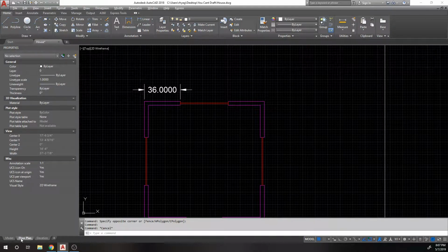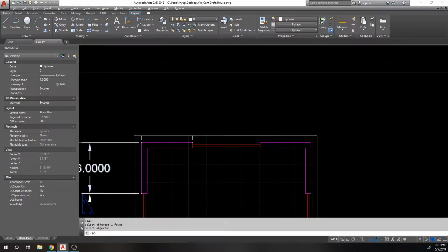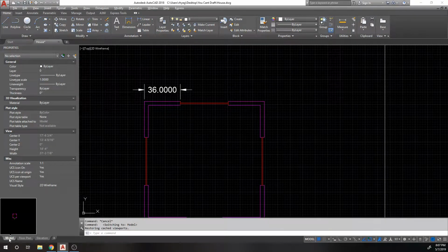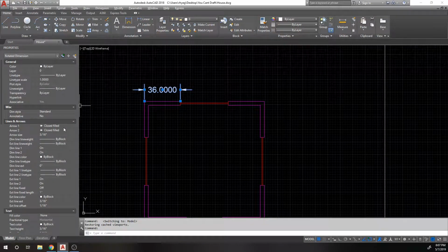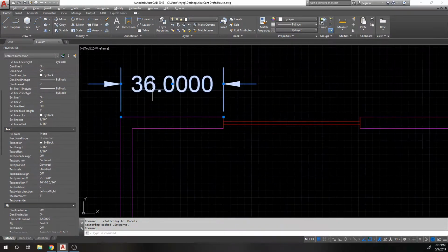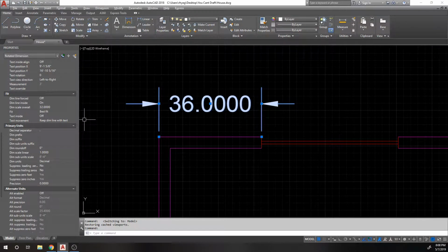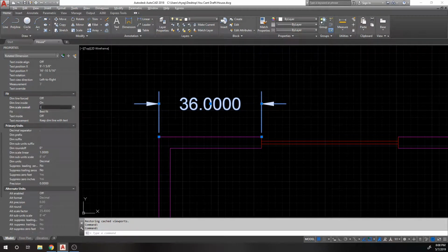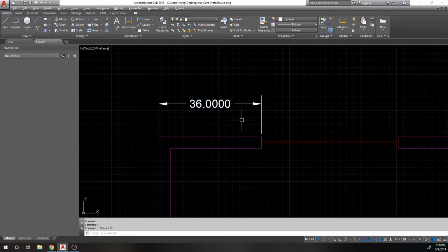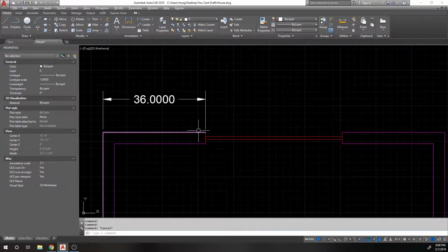You see I was over in the floor plan, and if I did one from here, let's see, dim linear from here to here, it basically looks exactly the same because I chose my scaling to be that scale factor 32. It doesn't have to be 32 because it's just graphically making everything bigger. It's scaling up the arrow, the lines, the text. Everything's getting scaled by 32, but the dimension doesn't actually change. So I could change this to 24 and make it look a little better, or 16. Right now it looks decent. It looks more like a real dimension.